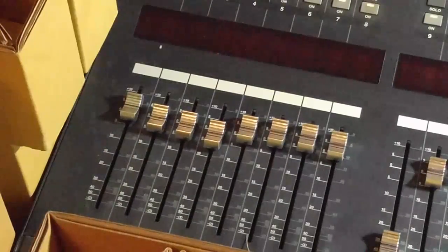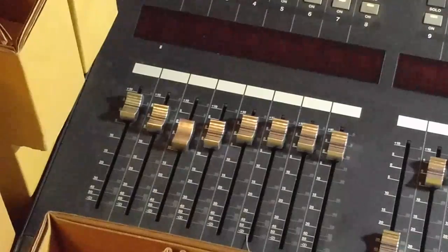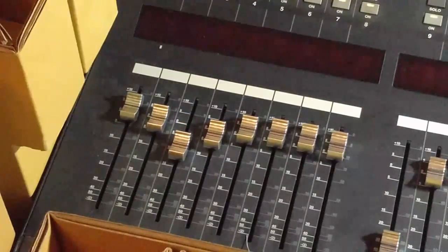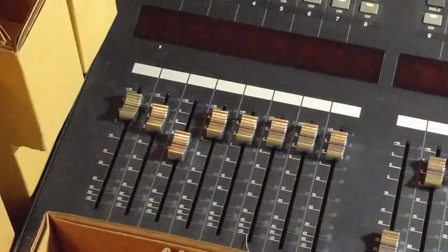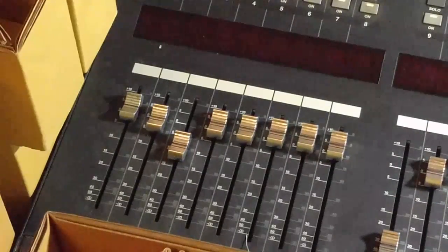It doesn't go all the way down, and it does stuff like that, which we don't like. That's not very nice compared to all the other ones, which are nice and smooth and don't really care where you drag them. So what causes that? Well, more than likely, it's going to be dust and other gunk that's mixed into the resistive track of the actual slider knob. Because even though it's a mechanical fader, it's still functioning in an analog way.